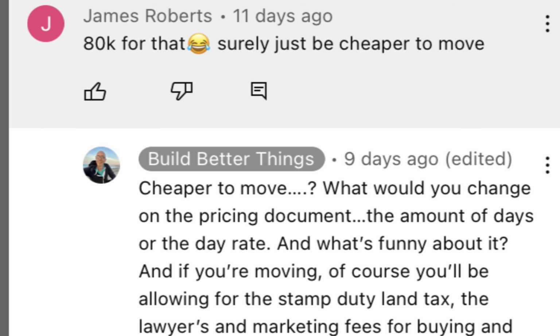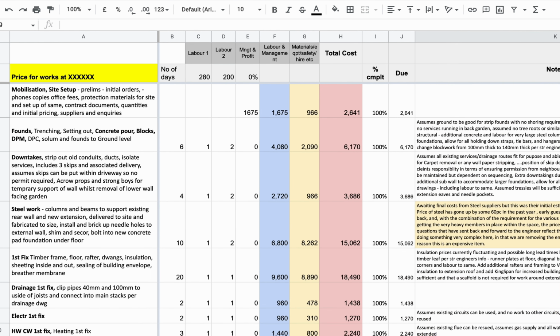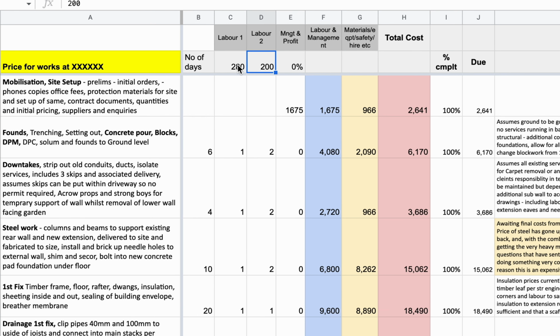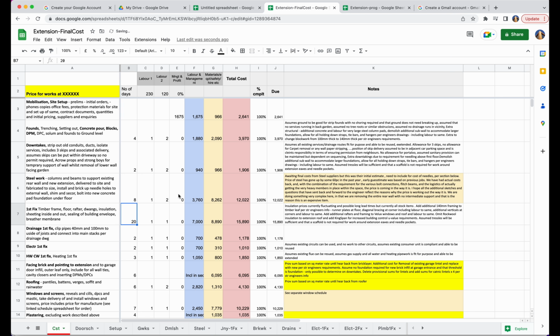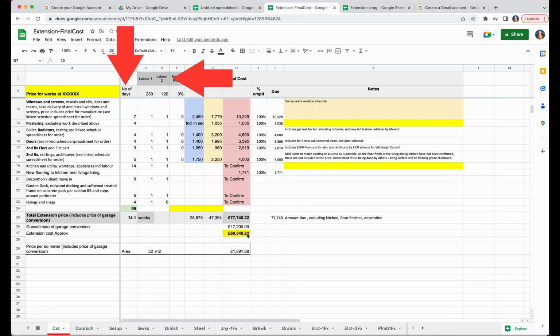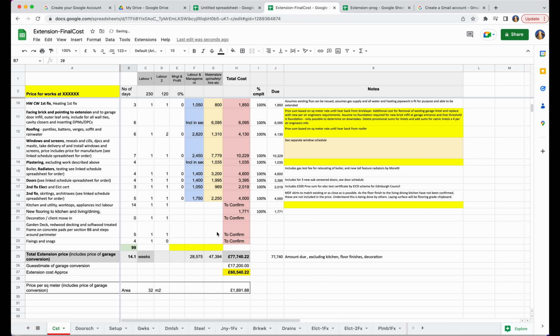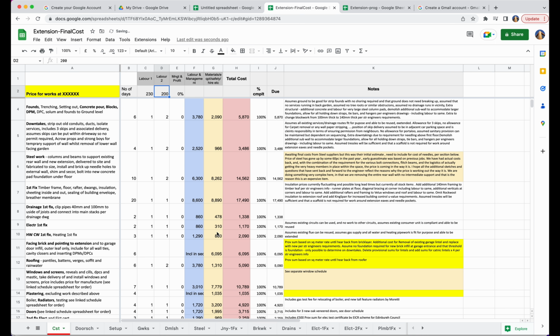Your opinion on the final price of any build, when you have a document prepared in this way, is kind of irrelevant, since if you think the price is too expensive, or cheap for that matter, then you can explain and adjust using this system really objectively as to what you would do if you were in control. So what you think is the correct day rate for the labour and what the correct time for each task could be. Those two options really are all that can change as materials are fixed because of how we measured them, as we saw earlier.